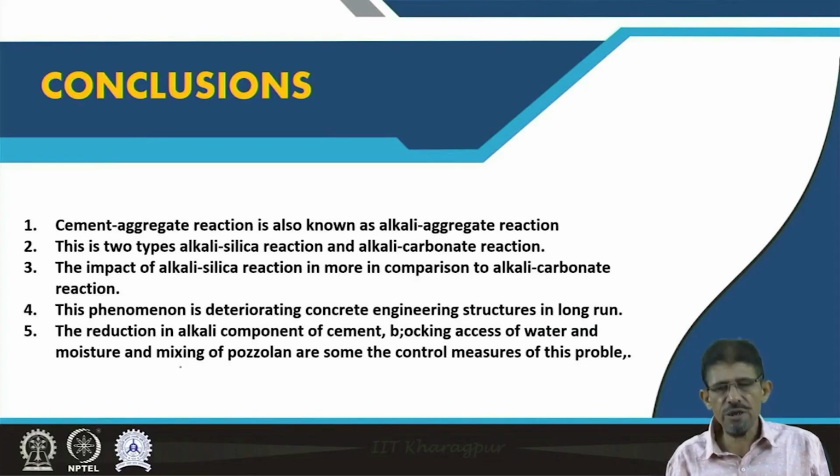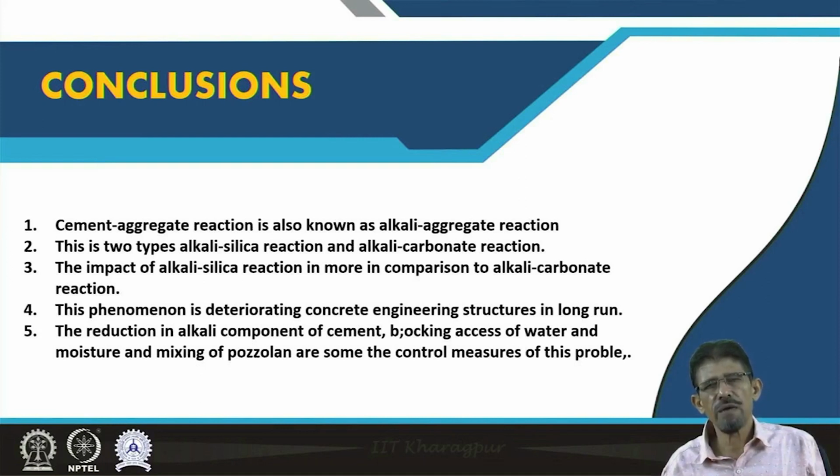The reduction of alkali component of cement, blocking access of water and moisture, and mixing of pozzolans are some of the control measures to this problem, and will save money as well as give some control on environmental issues, etc.